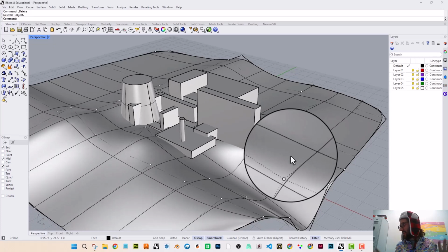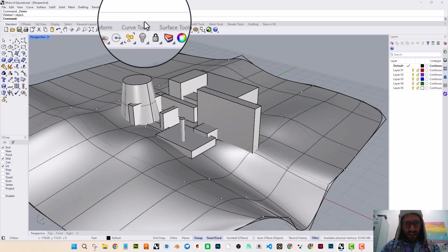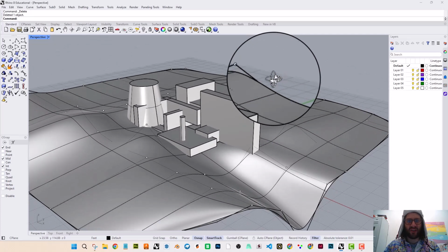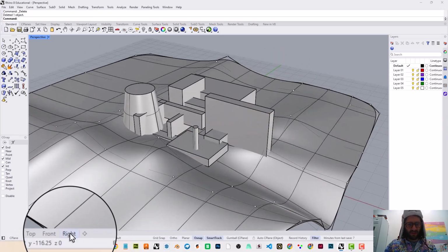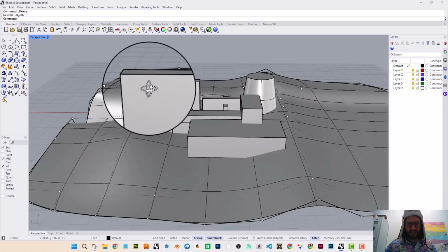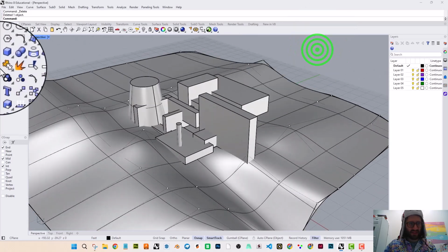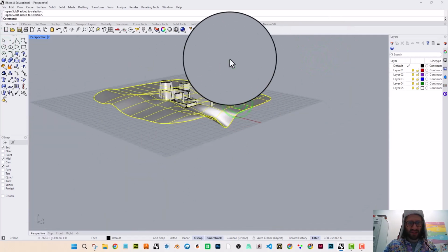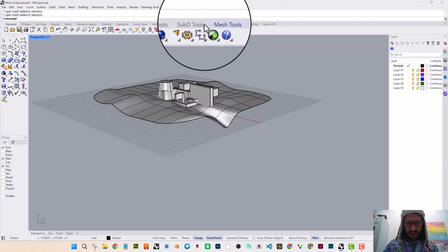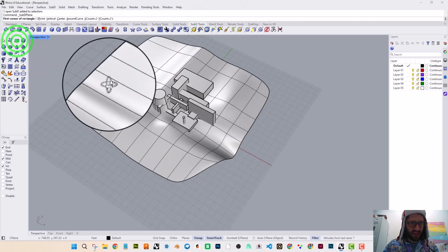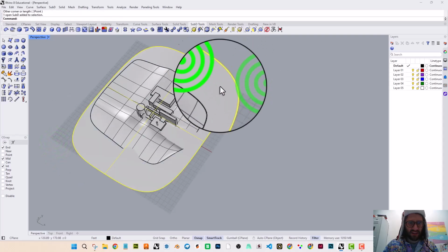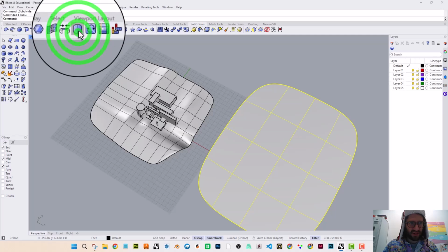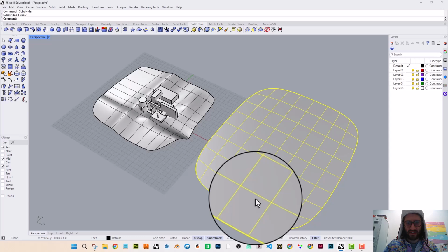So I'm gonna need to rush through this a little bit, but I think this is important for you to see. Okay, so I'm going to make an axon drawing with line weights that looks good in Rhino out of this, and it's gonna require some basic stuff first. In order to make this surface, I went to SubD tools here, and I made a surface there. It looked like that, and then I clicked this button, the subdivide, SubD, just a few times to get like that.